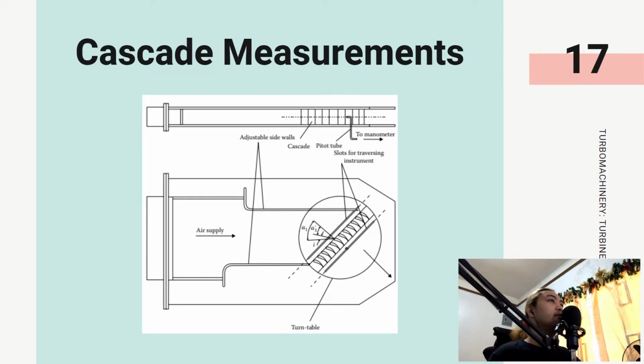Now, before going on to any design regarding the blade of the turbine, we must first consider the effects of different blade designs across airflow angles, pressure losses, and energy transfers across blade rows, in which one should resort to cascade wind tunnels and the cascade theory.